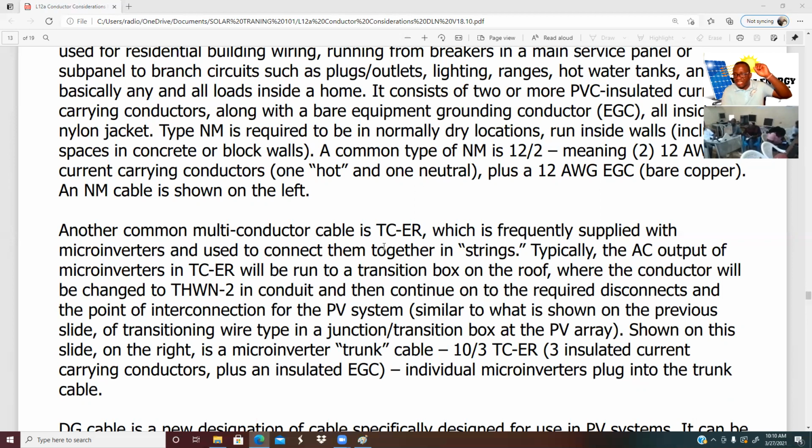Every panel has an individual inverter, called the microinverter, that inverts the current from DC on the roof, and the cable that comes into the building to the panel box or your junction box brings in AC current. So I can have 10 PV modules in an array, and each individual module has a microinverter.